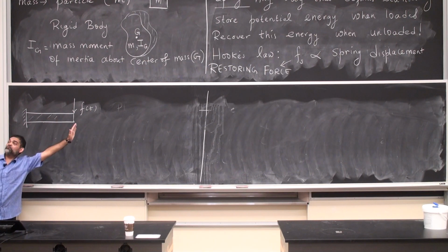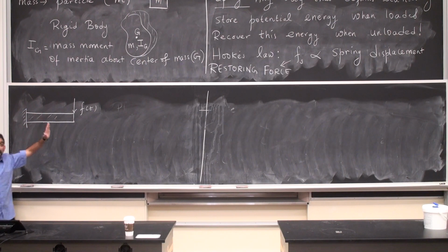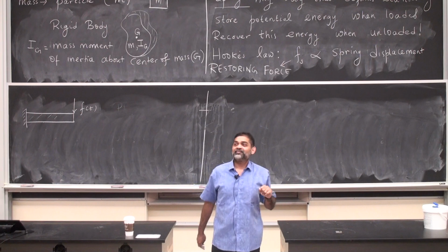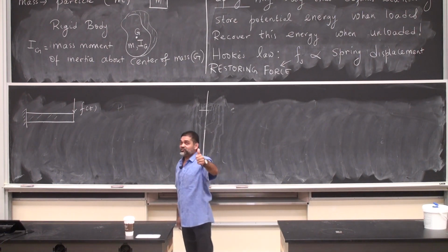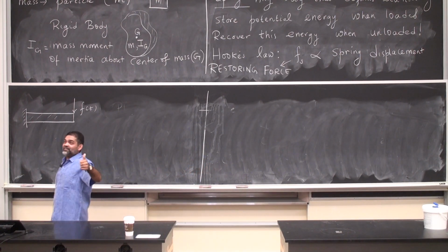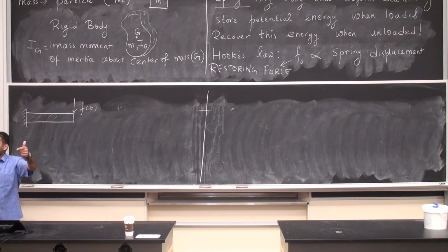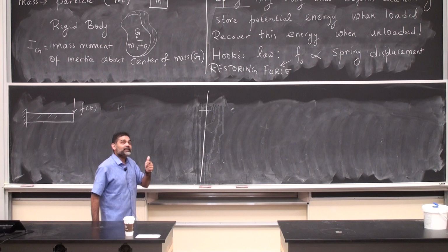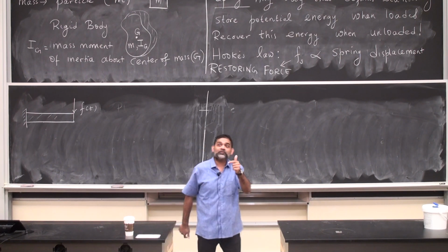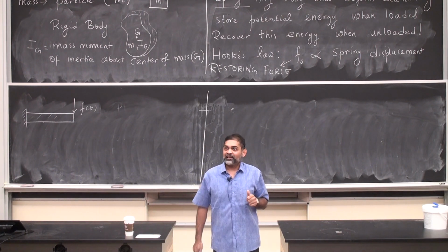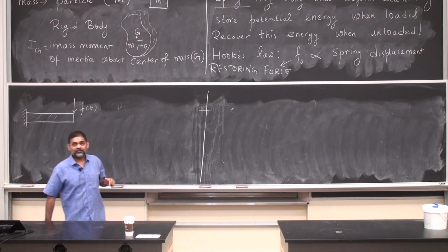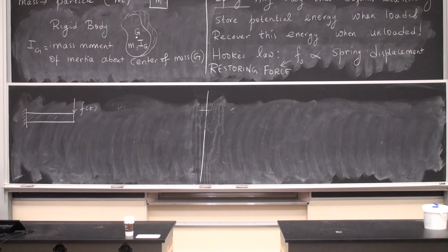So the deflection of the beam is spatially distributed. Not only that, it is also a function of time because the force is a function of time. So what do I see here? I see a system that is dependent on space, that is dependent on time, which means there are multiple independent variables, which means the governing equation that I obtain for this is going to be a partial differential equation. And it's going to be a fourth order PDE. I'm not going to look at it first. I don't like it. I want to simplify it.